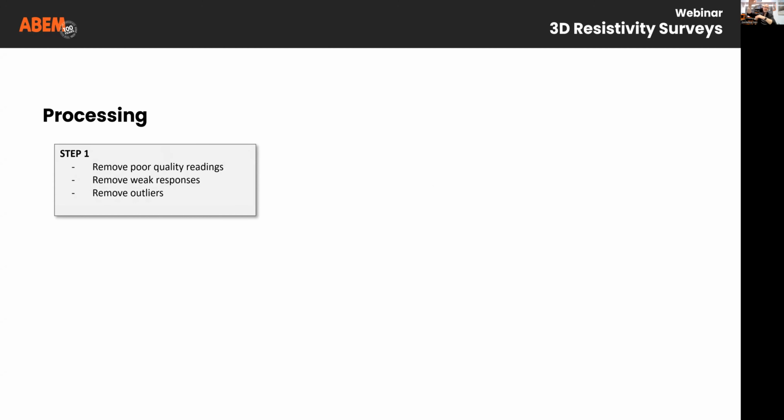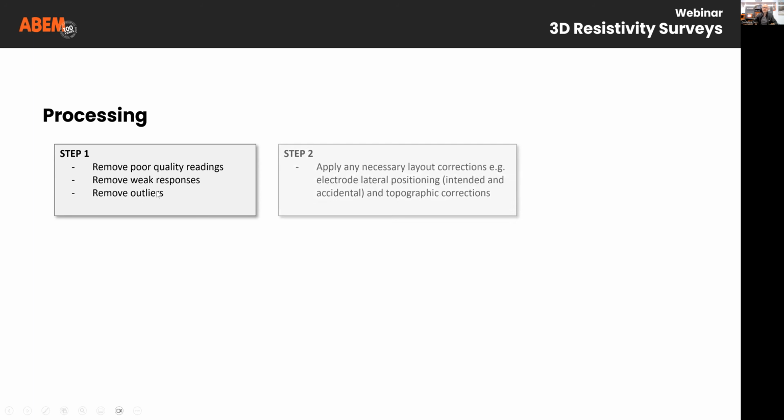And then we can look at the actual apparent resistivity spread, and we can look for values that are particularly low, where there's a big jump down from the main bulk of measurements, or any that are particularly high and there's a big step up without anything in between, because apparent resistivity values don't change very rapidly from one cell to the next, one measurement position to the next. They should vary relatively smoothly. So we shouldn't see any big jump at the top or bottom of our spread of apparent resistivity values. So we can get rid of those straight away.